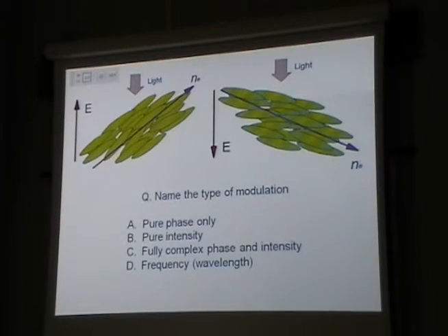So here's an example of a liquid crystal modulator. I have molecules pointing in one direction. ne is now pointing this way. Here's my applied electric field, so therefore the molecules form an equilibrium state like so. I reverse the electric field polarity, and what happens is that those dipoles now interact, force a torque on the molecule, and make it rotate. It's a nice liquid, so it does so. And my ne is now pointing in a different direction.